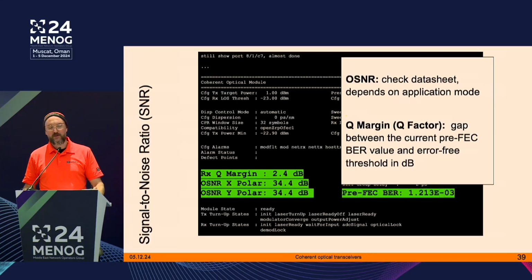And the bit error rate before we entered the FEC is here to the power of -3, which is alright, and then the FEC is very powerful. So we get at the end of the day a bit error rate of 10 to the power of -12. So we do a lot of correction in there, and it's needed.